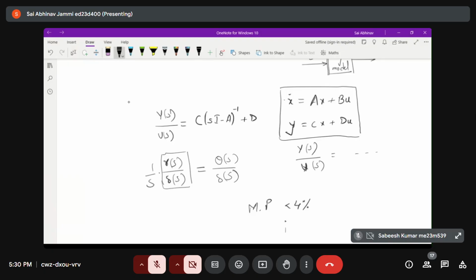Okay, sorry. So in this exercise, when we design the PI and P controllers, last time as we discussed, we directly went to the RL tool. Then if you remember, when we put the constraints, the areas where my poles have to be placed so that the constraint will be met appeared with shaded color and so on.